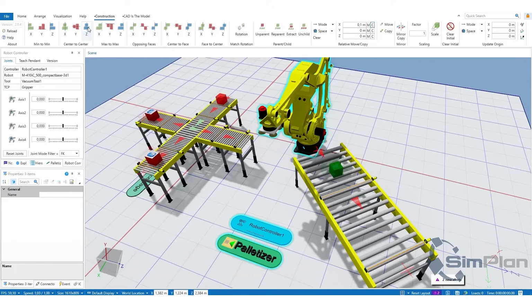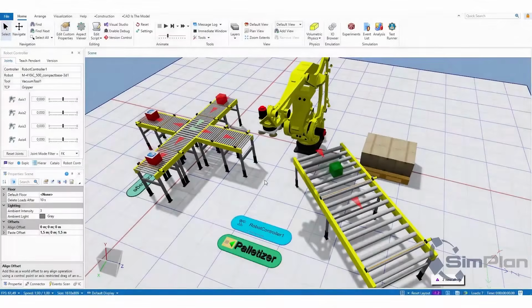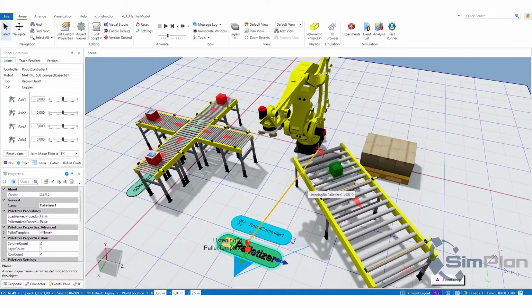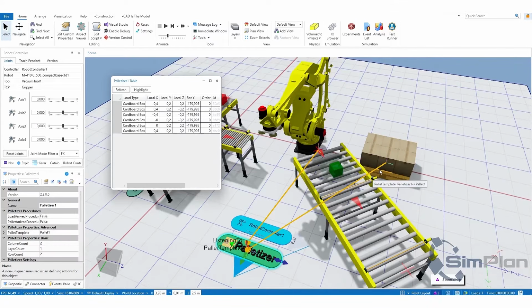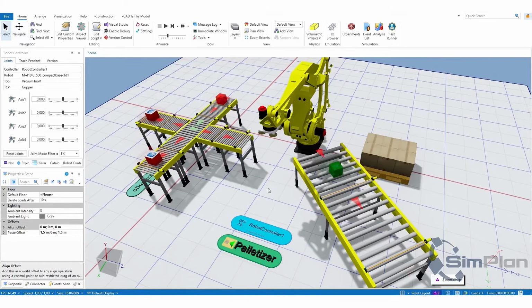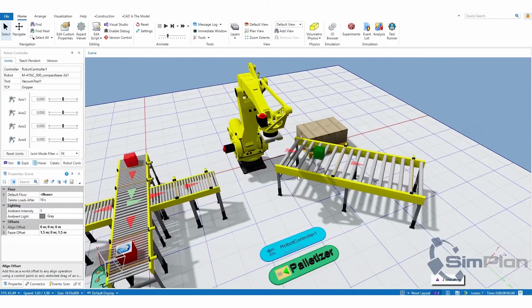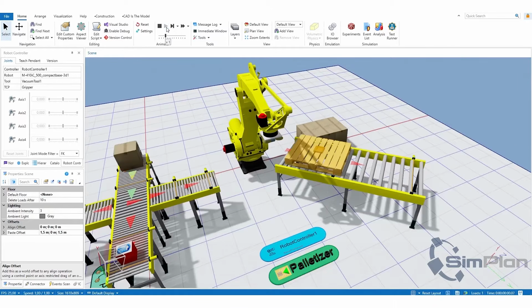Emulate3D then calculates the trajectory curve using inverse kinematics with the help of an internal solver. Alternatively, various robot simulators can also be connected. In this case, they take over the control of the individual axes and the grippers. The simulated trajectory curves then correspond 100% to reality.